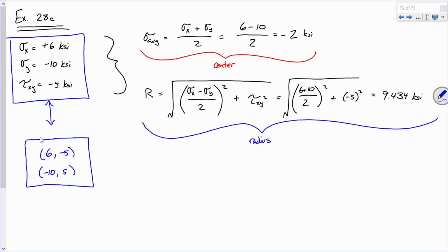So your x coordinates will correspond to your normal stresses, and your y coordinates will correspond to your shear. Now, shear's positive shear and negative shear, and honestly, from a design standpoint, it really doesn't matter. If I take a member and I go like that versus I take a member and I go like that, I'm doing the same thing to it. It's just a matter of flipping it around. So it's the same thing. Now, normal stresses, that does matter, because whether I take a member and yank on it versus taking a member and compressing on it, you can get different behavior. Things in compression like to do this little thing called buckling, which we'll talk about near the end. All right. What do you think? Nifty stuff, right?